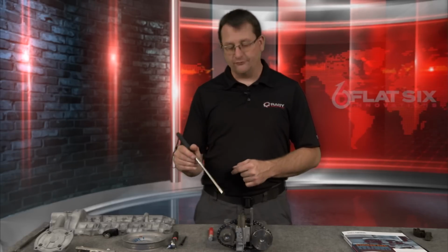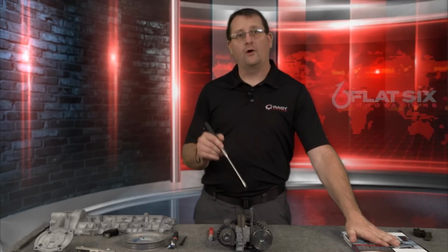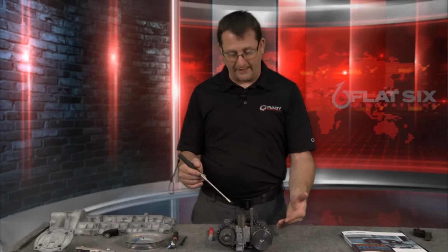The reason why we've marked ours is because the replacement chains a lot of times do not have the discolored links. So especially if you throw your old ones away, which you never want to do till the job's done, you're out to lunch and you've got to call me up or try to look in the Bentley manual or one of the manuals that's not clear about that. My workbook is very clear about that. My video is extremely clear about that, where these marks are, how to count them out, and all that sort of thing in case you did throw your chains away.